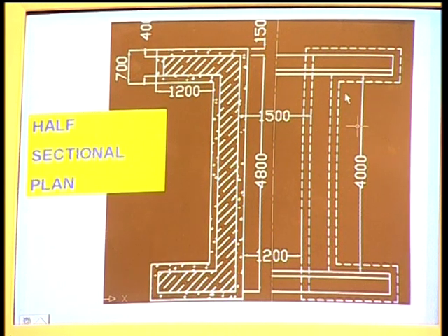Now, you can see the sectional plan at top. Here this dashed line is the plan of abutment and return, and also the CC bed. Now, this one is a parapet wall, and this offset is the projection, that is called the curb width. Curb width is given here. Here also you will get one parapet wall on either side, and the distance between the curbs is 4000, that is 4 meters is the width.